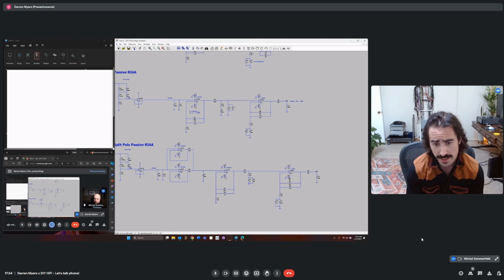And then we get to the more advanced side where we want even lower noise than that. The next step would be to use higher spec integrated regulators. You can get, from Linear Technology, for instance, a lot of excellent high bandwidth regulators that will perform better.